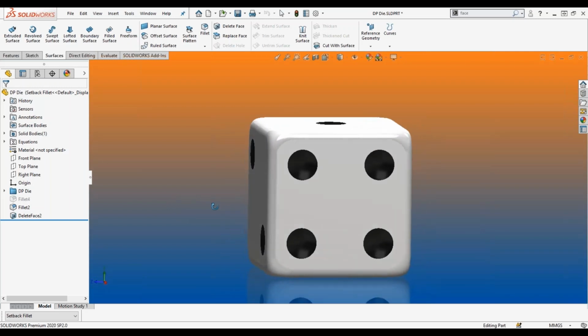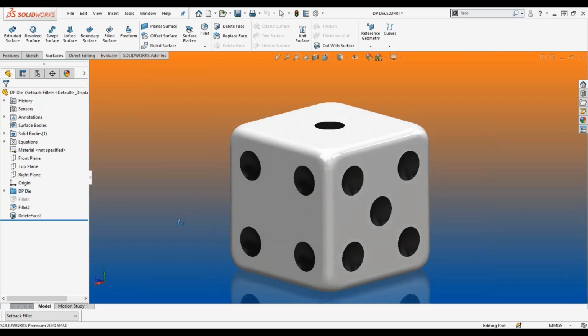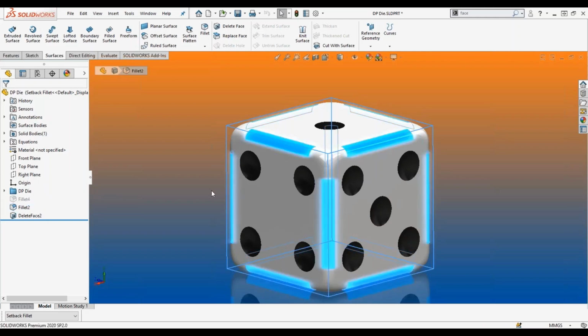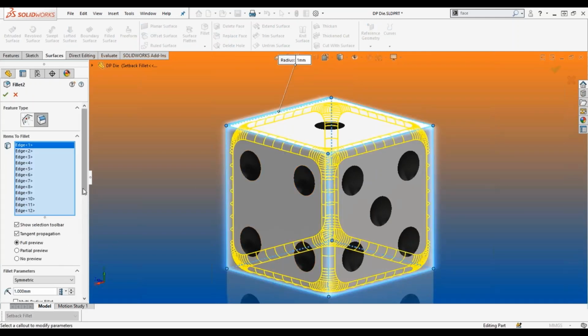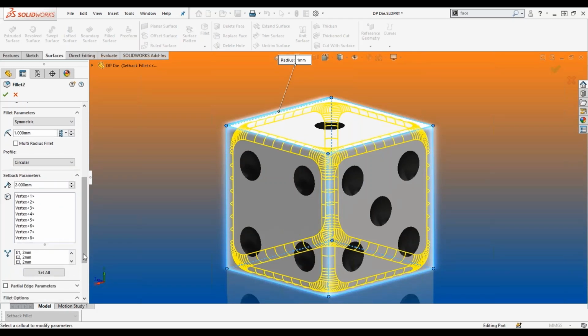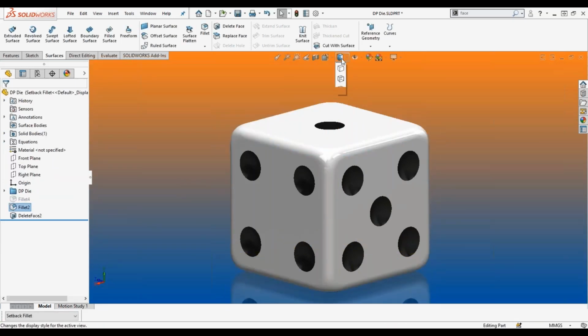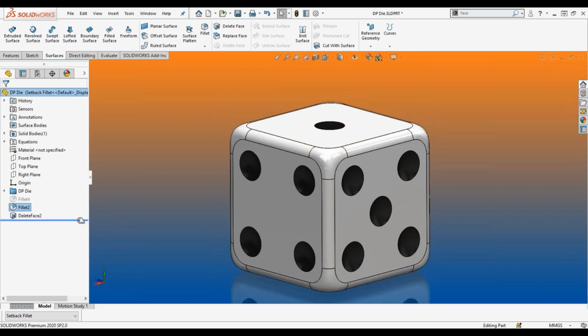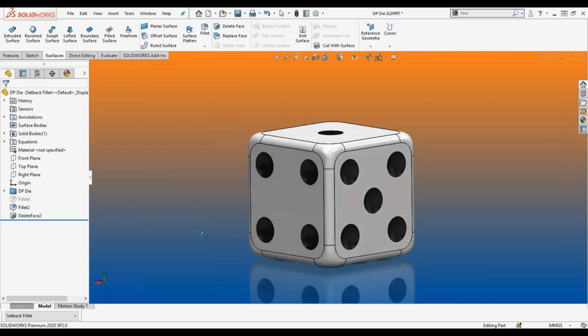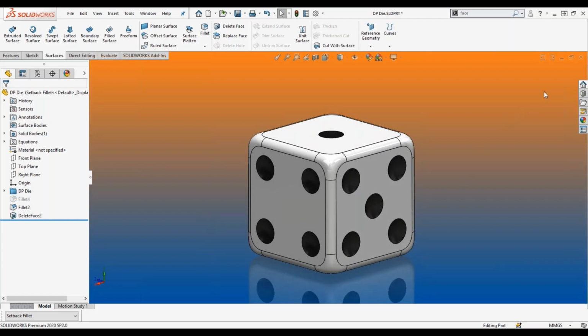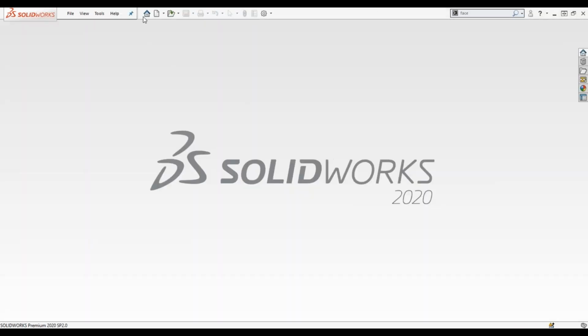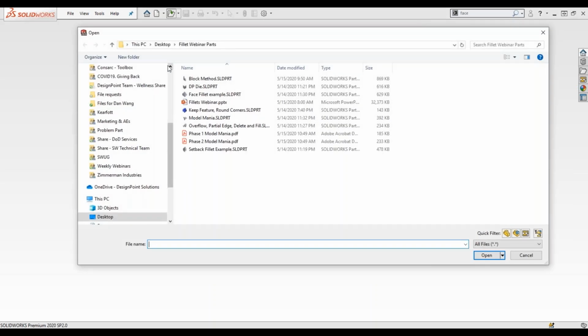Right, just by adding a setback, it makes it look even that much more realistic. And if I edit this feature, I just set it back 2 millimeters, I believe, for every vertex. And then I cleaned it up with a little bit of a delete face, so it doesn't have those edges that it normally creates. Right, it cleaned it up with the delete face tangent fill. So that's our setback fillet. Pretty neat feature. Let's keep going. So I actually got time to hit every example.